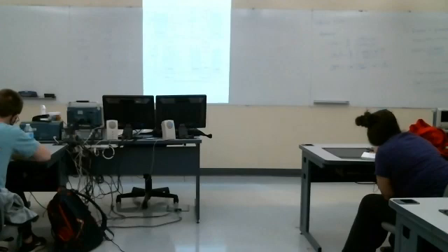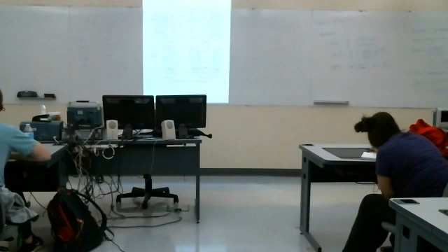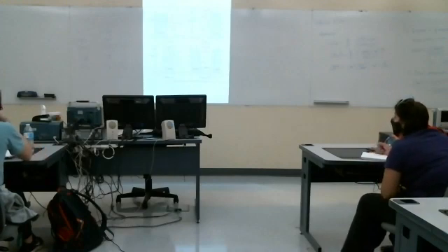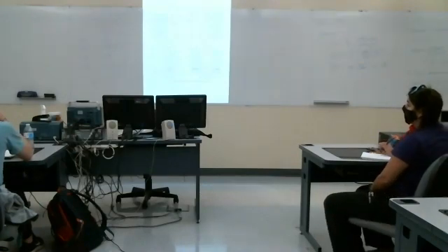So on semi-log paper, we'll find this point omega c. On semi-log paper, 10 omega c is the same distance above omega c as 100 omega c is above 10 omega c. This distance is the same as it would be for omega c over 10 and omega c over 100. So they're equally spaced here in what are called decades of frequency.